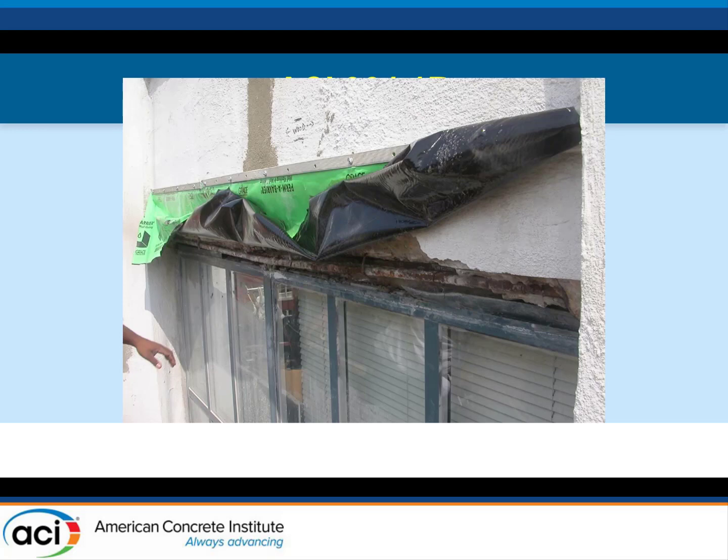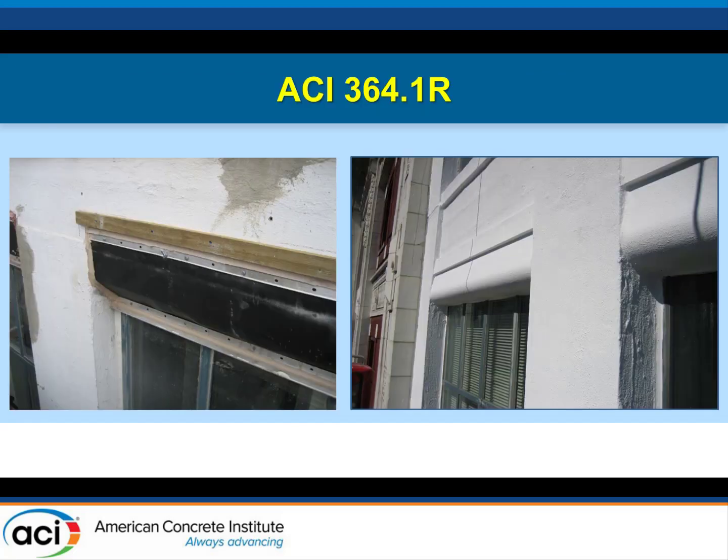Our owner wanted 25 years, so we had to get creative in what we did. We gave him solutions. One was to go in and take the windows out and do the concrete repairs they really needed to do. He didn't like that at all. So we had to get a little bit more creative. So we wound up putting in a waterproofing system, sort of membranes there that we had attached to the window system, regulated into the concrete. We used fiberglass panels on it, and it actually looks pretty good at the end of the day. The service life prediction on it, we think you get 25 years out of it.